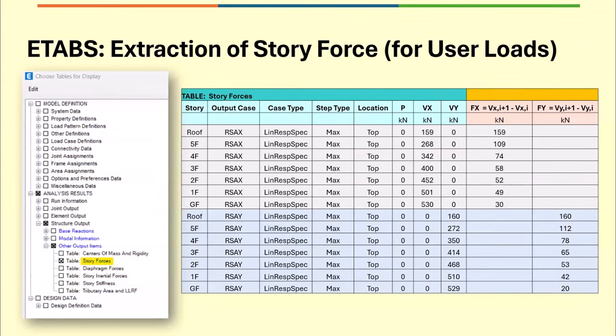In the ETABS, one heads up that we want to give is that when dealing with the response spectrum cases and for the foundation analysis, we suggest that these dynamic cases are converted into equivalent static. So for converting, you can extract the story forces for these spectrum cases.